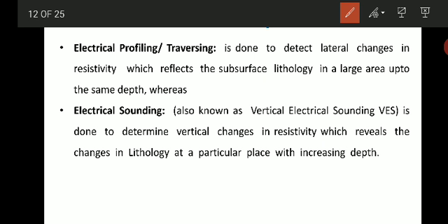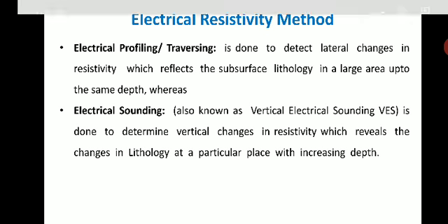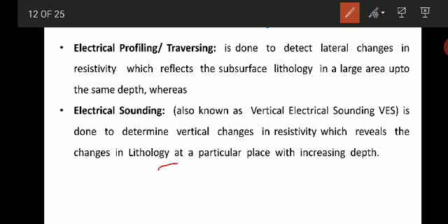Okay, then what is meant by sounding? That is vertical electrical sounding, VES. This is done to determine the vertical changes in the resistivity, which reveals the changes in the lithology at a particular place with increasing depth. Suppose this is the ground level.